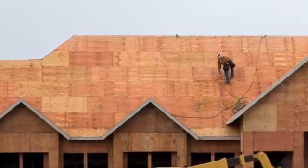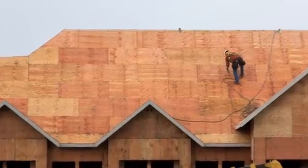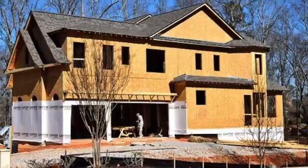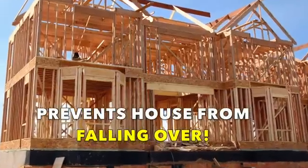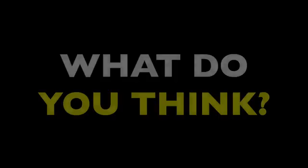Sheathing is a layer of plywood or strand board that covers the entire framing system from the outside like a skin. It's the layer beneath the house wrap and the siding. Sheathing is very important, and it often does more than just close the house in. It also prevents the house from falling over. But that's a topic for another time because it's complicated and it deserves at least one video of its own. This video is about framing, and you've just heard about many, if not all, of the important framing members in a house. So, what did you think?